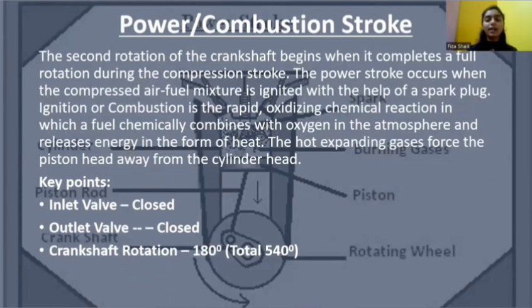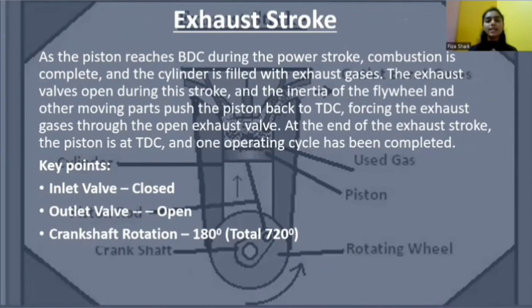The hot expanding gases force the piston head away from the cylinder head. Key points to remember in power combustion stroke are: both the inlet valve and the outlet valve are closed, and the crankshaft rotation is 180 degrees. The last and final stroke, which is exhaust stroke.